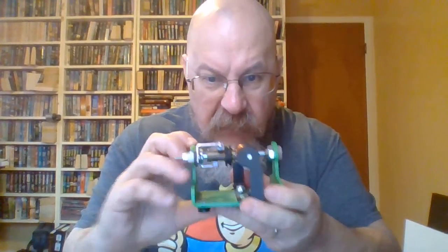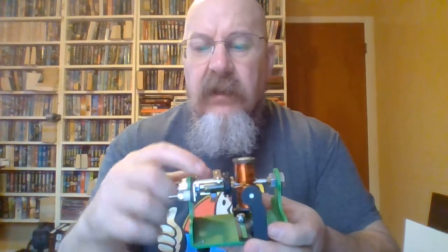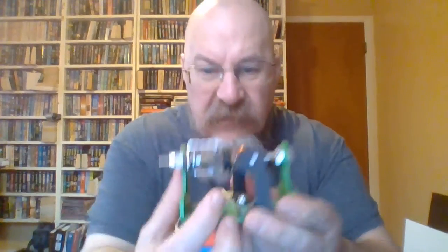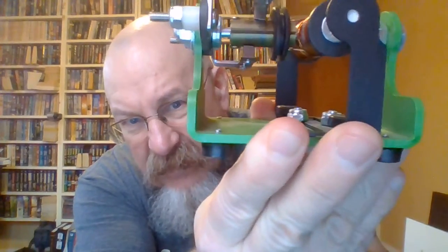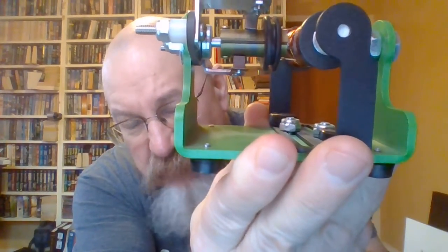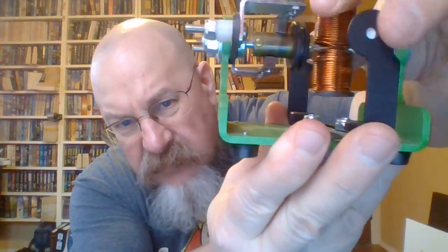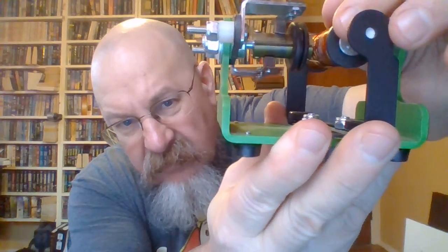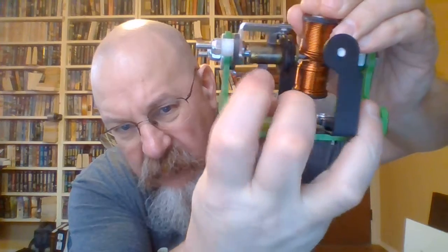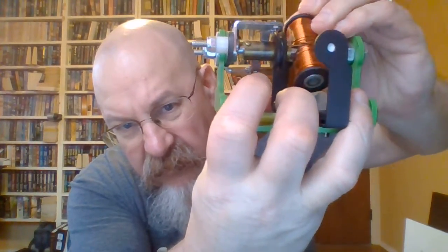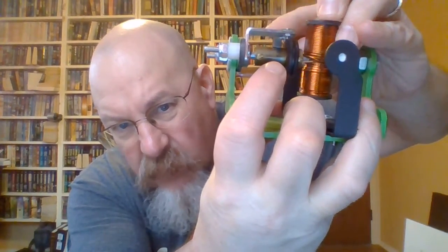And then down here on the bottom part, right there, there's a split. You see that line across? That's the split in what we call the commutator. Notice that as I rotate this halfway, the top half is going to move in contact with this down here, and the bottom half is moving in contact with this one up here.